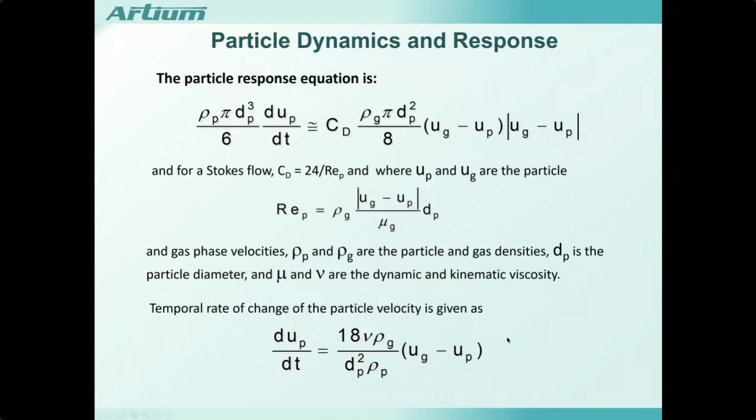In a turbulent flow or an accelerating flow, there must always be a particle lag, that is a difference between the gas phase and the particle phase, to provide that restoring force to get the particles to respond to the next acceleration. So when someone says, I don't believe my particles are lagging the flow, I think they're representing the flow well, you have to question that and say, well, they're not responding completely to the flow, but what we really need to do is keep the particles small enough so that difference remains relatively small.